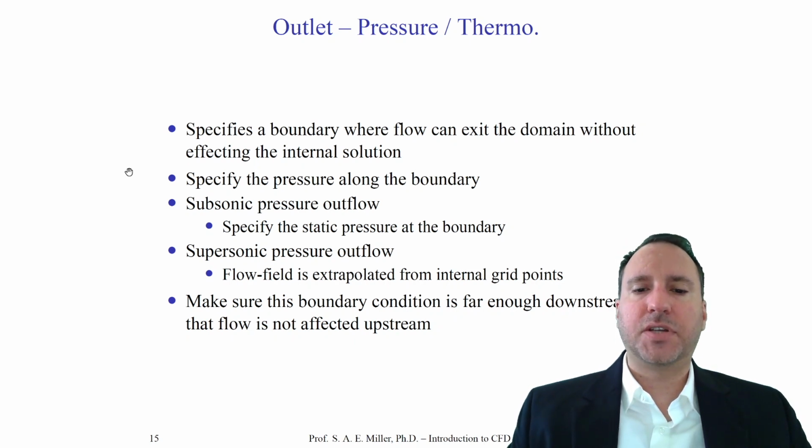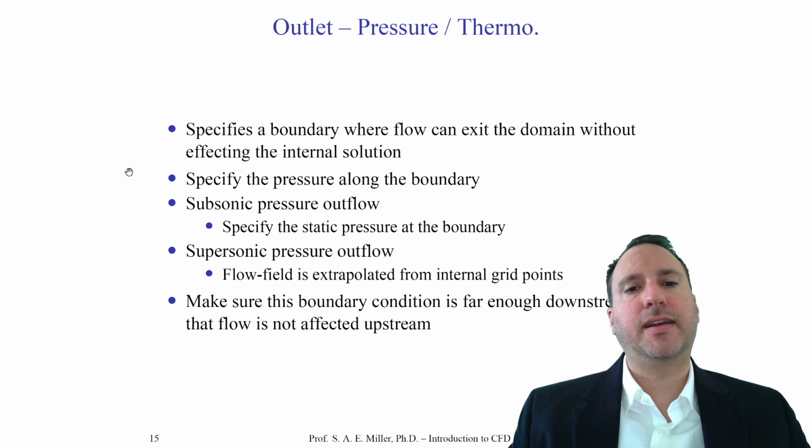If the solver detects that the flow is supersonic, it'll only extrapolate the condition. If the flow is subsonic at the static pressure condition, it'll simply enforce the static pressure. So you can get into trouble with this condition where the boundary condition is fluctuating back and forth between subsonic and supersonic flows, e.g. the transonic condition.